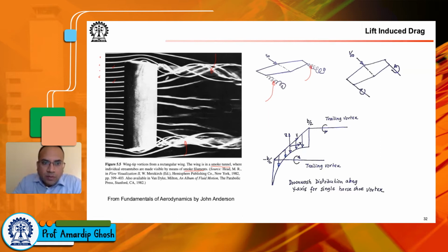So that's the Lanchester's model where you have these trailing vortices. In Prandtl's model, you also have vortex tubes that are shed at different locations from the span, of course of various intensities, and then they eventually wrap up into these trailing vortices at a decent distance from the wing. When I say a decent distance, these are expressions that are ambiguous, and they're ambiguous for a reason. When we say decent distance or moderate distance, in experimental aerodynamics you will say, how many chord lengths behind the trailing edge does that happen?